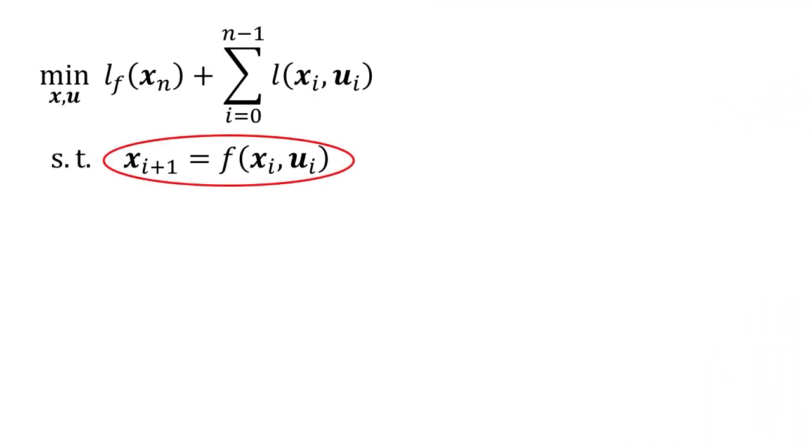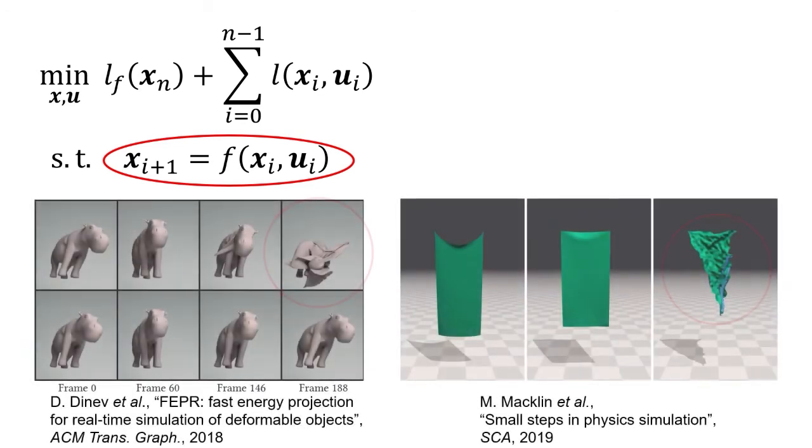The main challenge when we want to simulate deformable objects for dynamic manipulation is that they suffer from numerical stiffness issues. As a consequence, when applying explicit integration to these types of systems, the simulation tends to be unstable and blow up quickly.